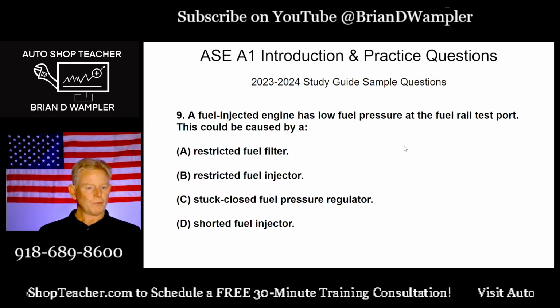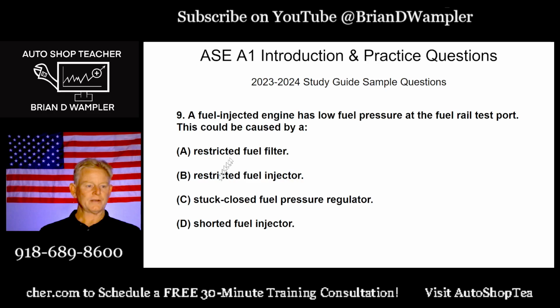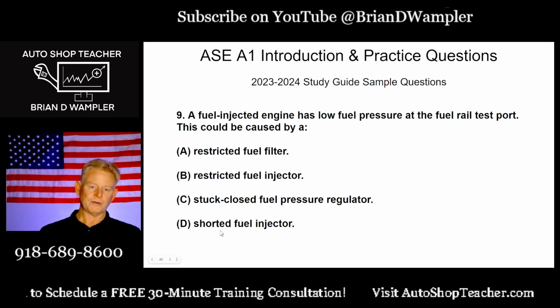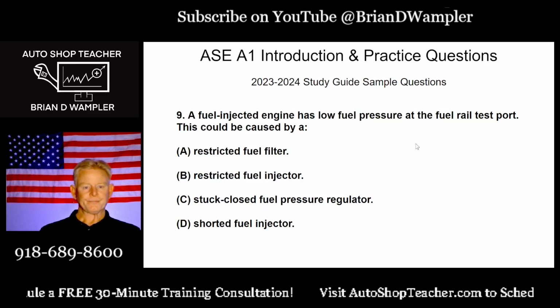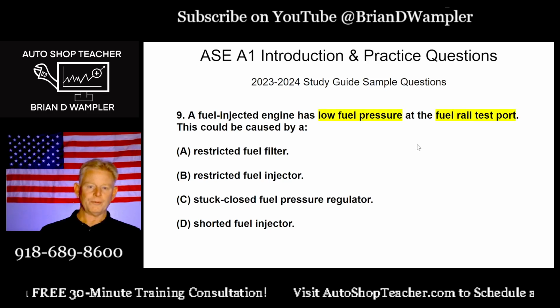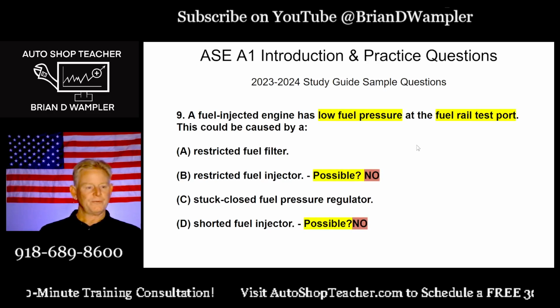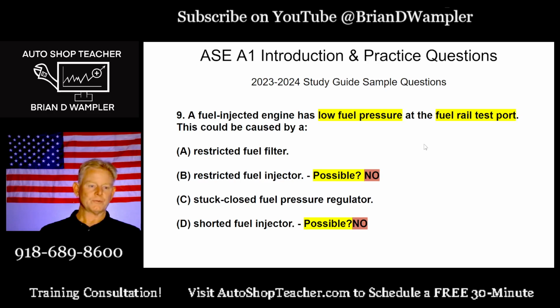But just make sure you're looking at the terms that they're using. Restricted, restricted, stuck closed, shorted. Wait a minute, shorted? We just switched to an electrical answer on D. Okay, low fuel pressure at the fuel rail test port. So restricted fuel injector, I'm going to go ahead and eliminate B. Hopefully you have already as well.